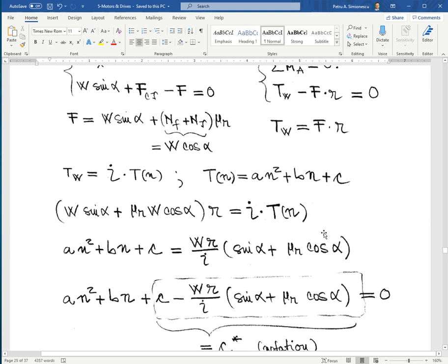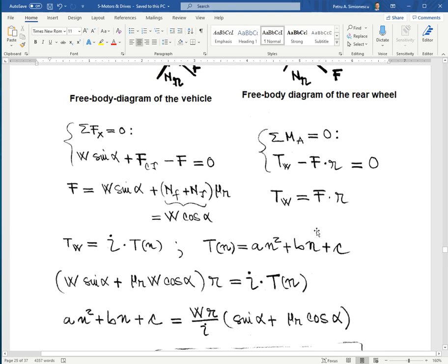You would have to go back to these early equations. We have the wheel torque being the maximum torque times i, okay, and then you go back, and I have the maximum torque now from the torque speed curve, and I solve for F and plug it in here, and I get an equation with A times cosine plus B sine equals C. We solved that type of equation, if you remember, when we analyzed the 4-bar linkage.